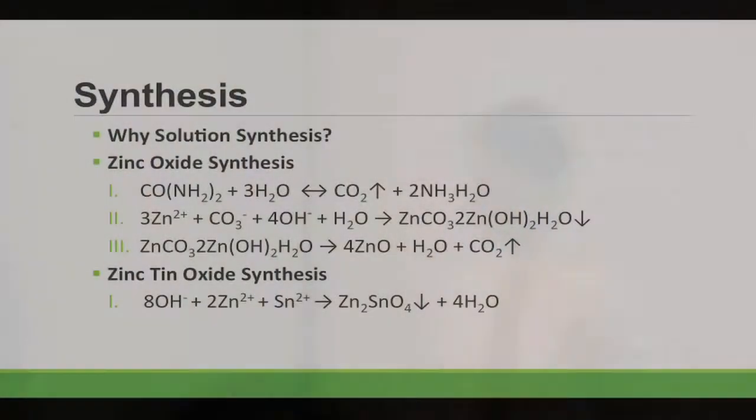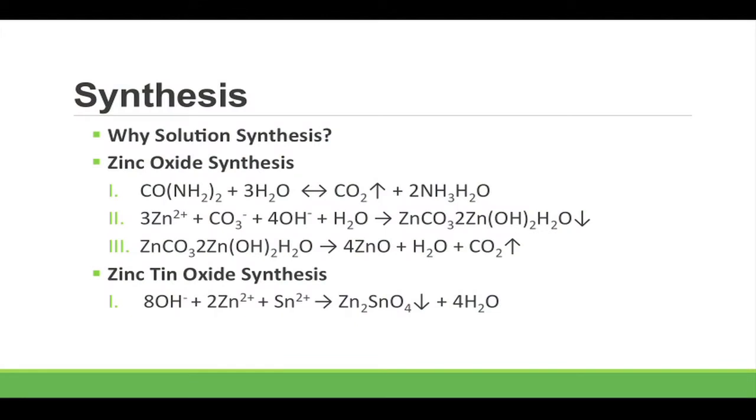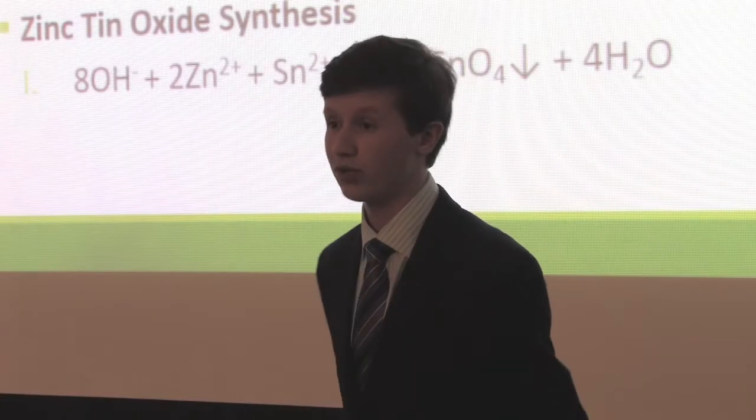So many conventional synthesis techniques for making zinc oxide nanostructures utilize vapor transport processes. But this occurs at very high temperatures, upwards of 1,000 degrees Celsius, because you need to generate zinc and oxygen vapor. What we studied in our research was solution synthesis, which deals with aqueous solutions and occurs at much lower temperatures that are usually below 100 degrees Celsius. So they're much more cost and energy efficient when compared to traditional processes.